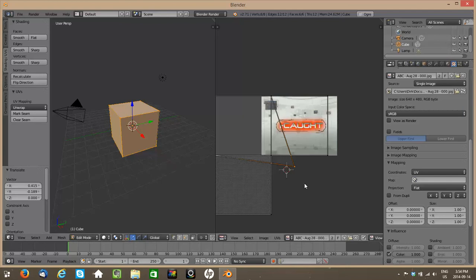And the idea, of course, is that we will ultimately want to position them to coincide with the image, right? So assuming that's our intention when we're rendering something, I can deselect, select the next one, and this will eventually work. So I can continue these operations until I've repositioned everything where I want it. The thing is, though, it's a dummy exercise. Nobody would really want to map this image to fit onto that cube. But this is the starting point of a UV mapping exercise for a model that's already been defined in 3D.